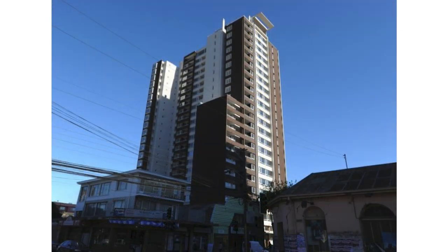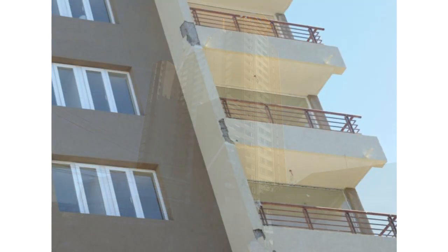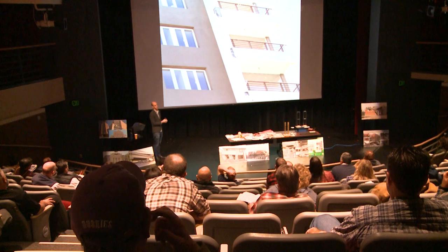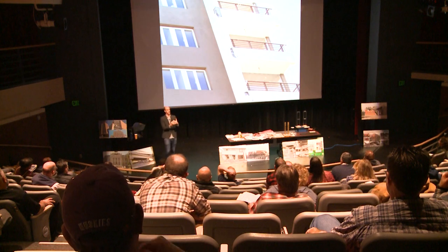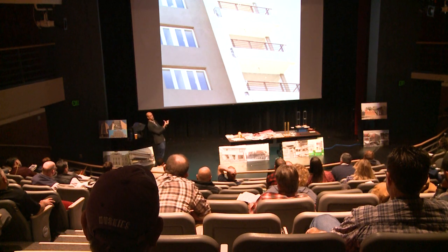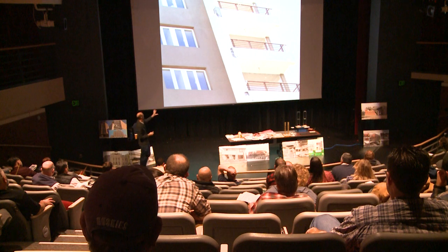So here's another high-rise building. This is also from that Chile event, a reinforced concrete shear wall building, 30, 40 stories, if you do the count. How do you characterize this damage here? You have these balconies connected to these walls at the joints. There's some damage. Relatively superficial, the plaster and maybe a little bit of the concrete cover, the concrete that's outside of the confining reinforcement. So it's, outside of the pop can, we have a little bit more concrete to kind of cover things up. So that's fallen and fallen off.